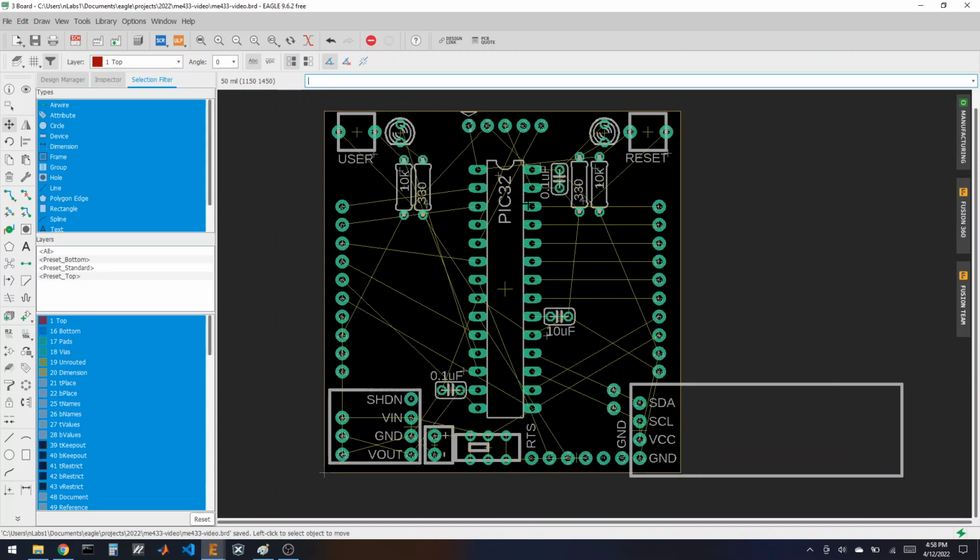Okay, so I've got placement in a pretty good spot, I think. The next step is to start to route things. So I could use this eyeball tool, the show tool, to click on a wire and down here it says the name, this is the B15 trace, and those are the 2 pins that need to be connected. And most of them are point to point, but the complicated ones would be like this.